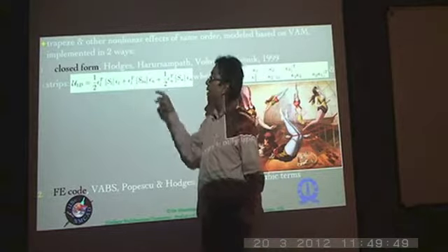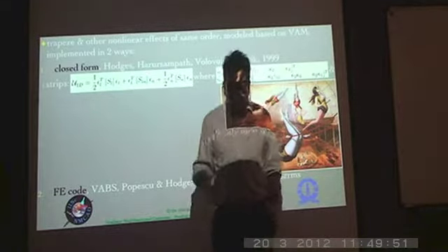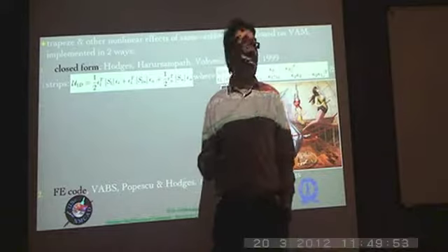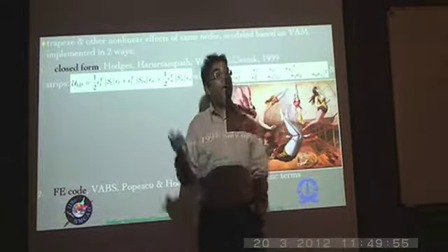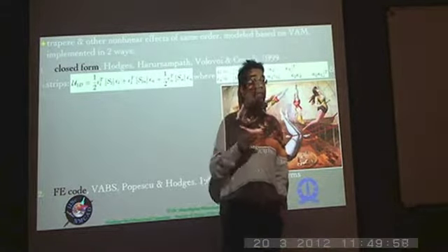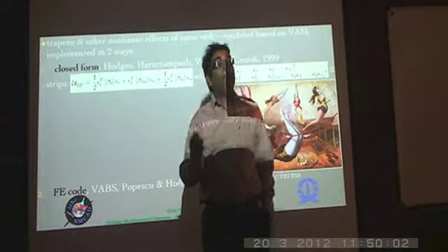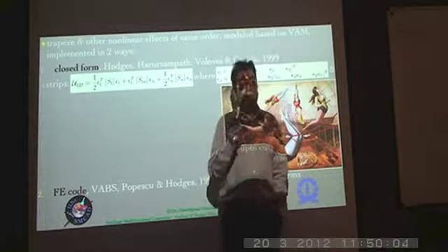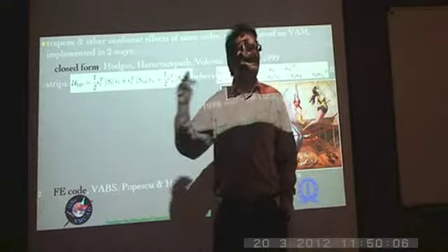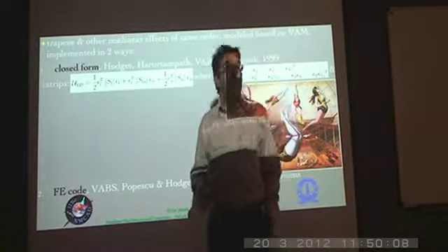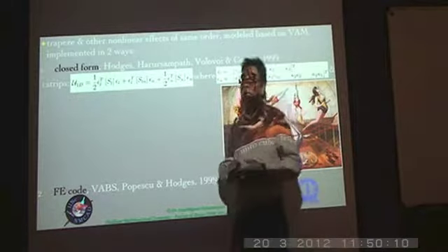In this particular case, as I said, there are two ways of expressing this cross-sectional nonlinearity. One is by making the stiffness matrix S bar itself functions of the 1D variables. The other is to retain it as constants and then add additional terms, other than quadratic, to the one-dimensional strain energy density. So that's basically what is done here.